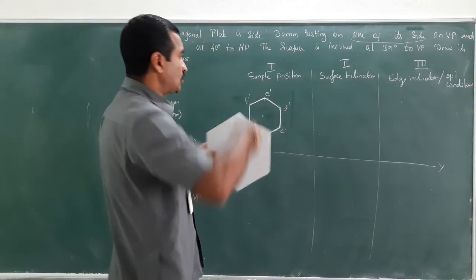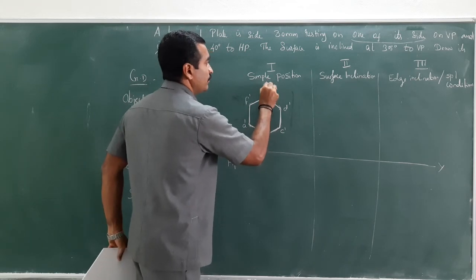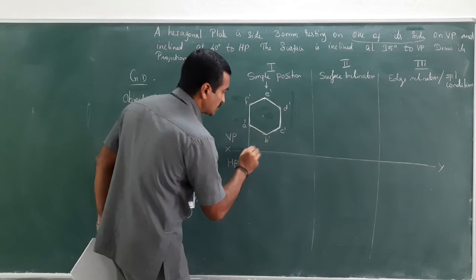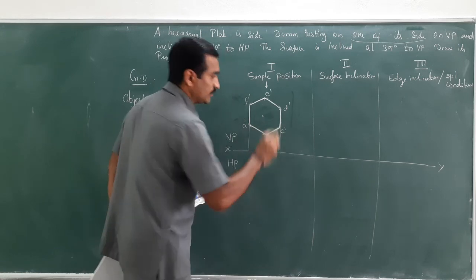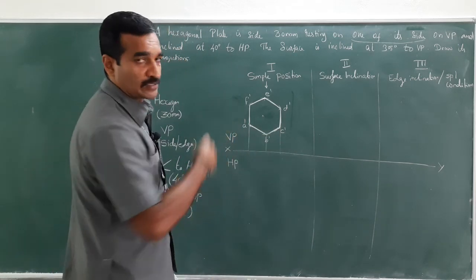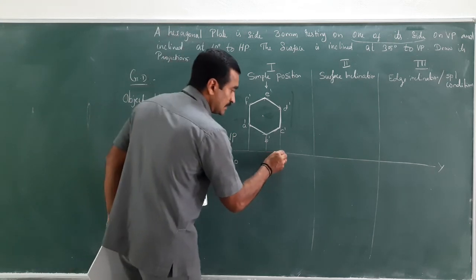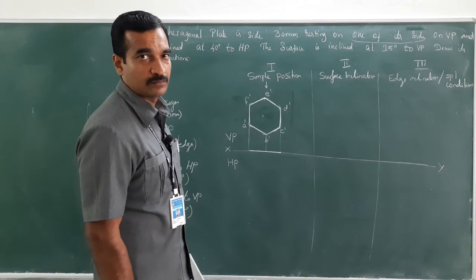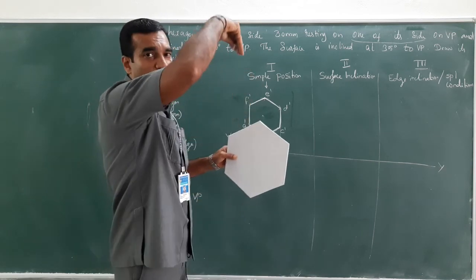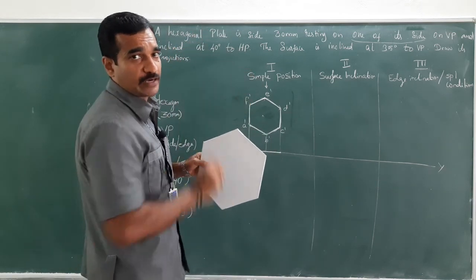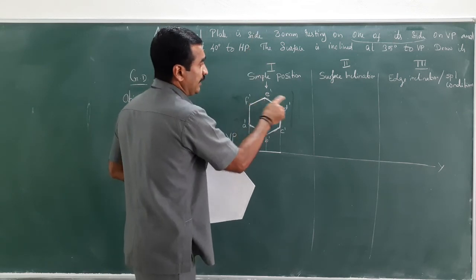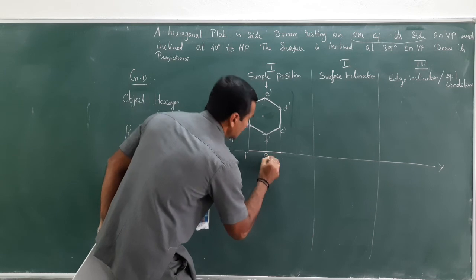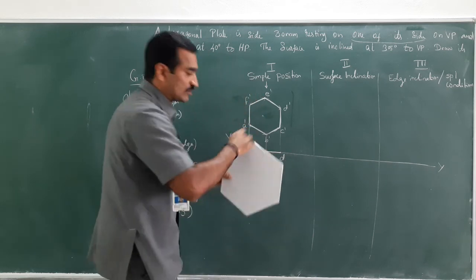Now when you look at it from the top, to draw the top view, you just project all the corners till they intersect the reference line. Now connect the line, draw a line. Now look at it from the top, what corners are visible? When you look from the top, F, E, D are visible. F is visible, E is visible, D is visible.